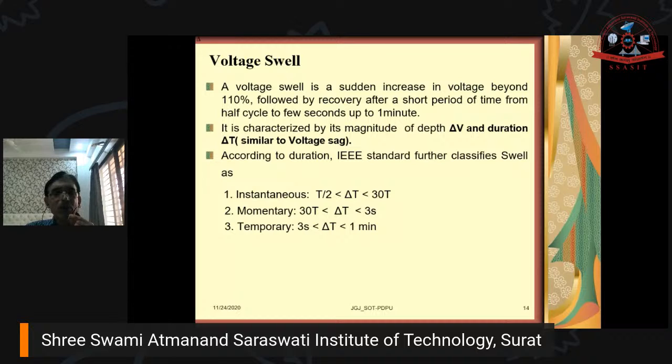If we divide 400 volt by root 3, then 230 volt, right? So 230 volt is the nominal voltage, and 400 volt is the three-phase nominal voltage. As per the Indian Electricity Rules, plus or minus 6% variation is allowed at the consumer terminals. For example, the declared voltage by the utility is 230 volt, so plus 6% means around 245 and minus 6% means 216. If the voltage is below 216 volt, then we can complain actually.